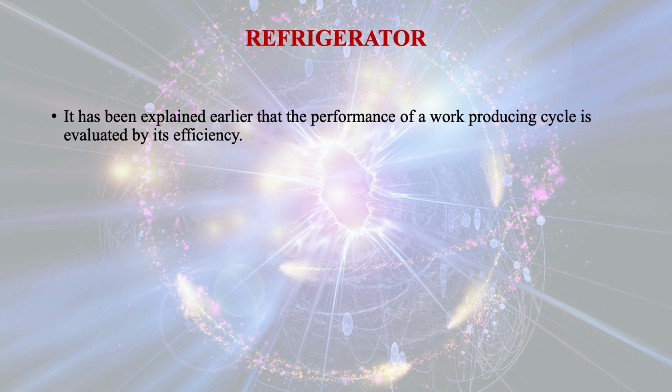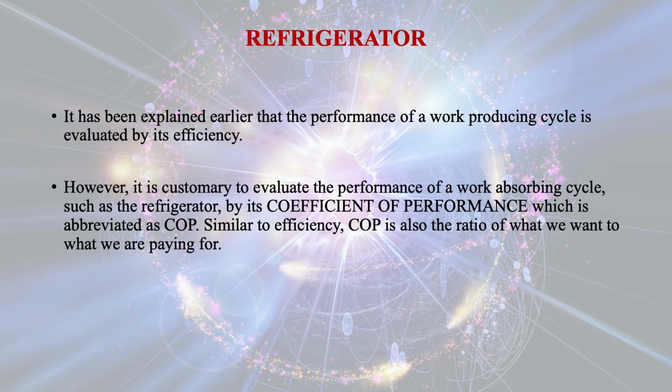It has been explained earlier that the performance of a work producing cycle is evaluated by its efficiency. However, it is customary to evaluate the performance of a work absorbing cycle such as a refrigerator by its coefficient of performance, which is abbreviated as COP. Similar to efficiency, COP is also the ratio of what we want to what we are paying for.